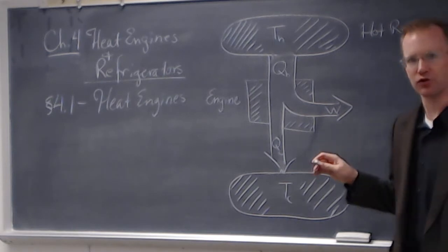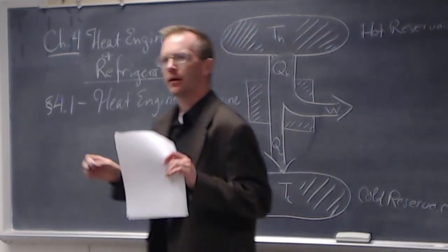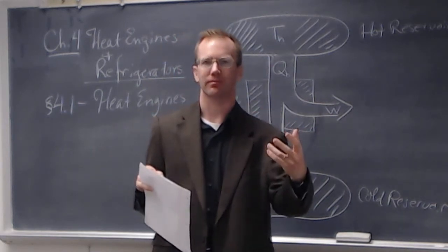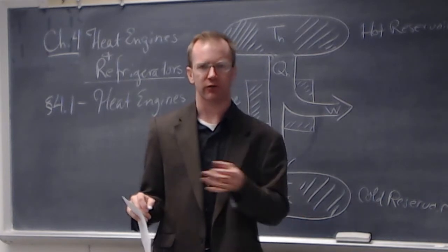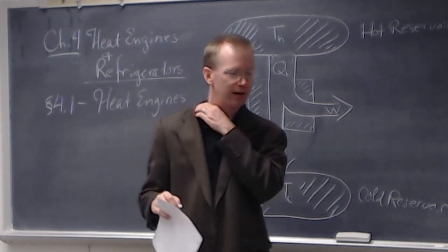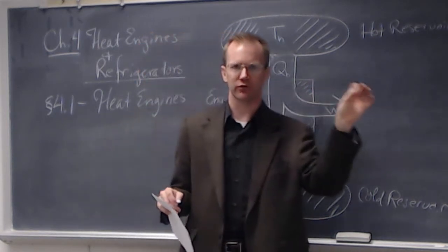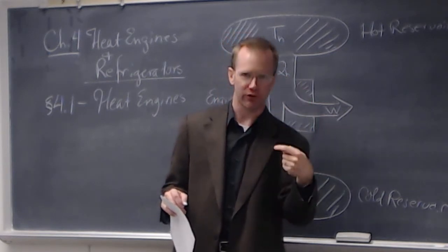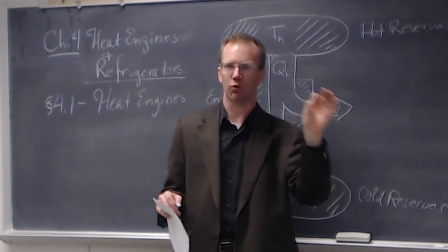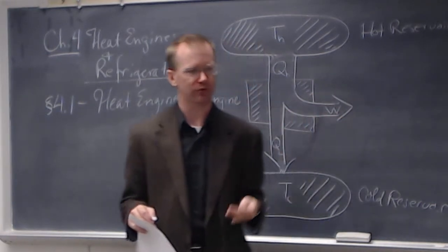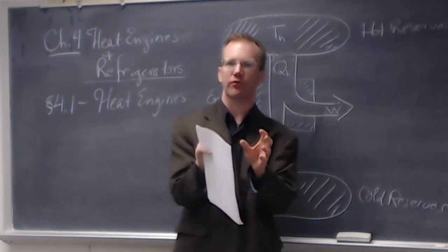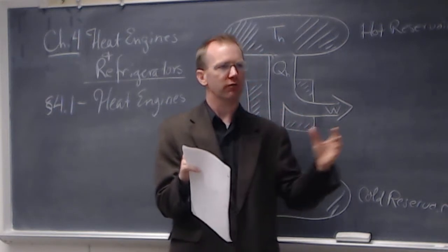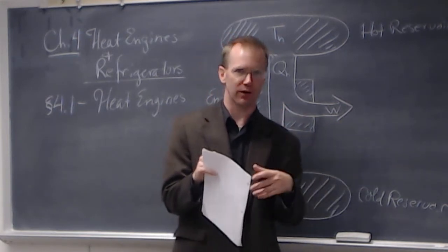Now, you've got to be careful in the terminology. When we were looking at the system in the previous chapters, we looked at the work done on the system. Remember the first law of thermodynamics, dU equals Q plus W. The change in the system's energy, U, is equal to the heat flow into the system, that's the positive sense, plus W, the work done on the system, also the positive sense. So if energy is added to the system through the flow of heat, then Q is positive. If energy is added to the system through a compression, then W is positive.